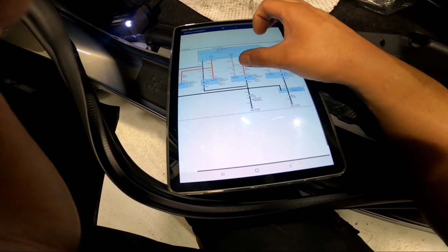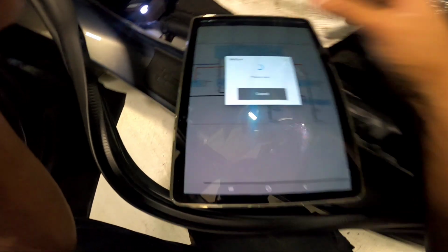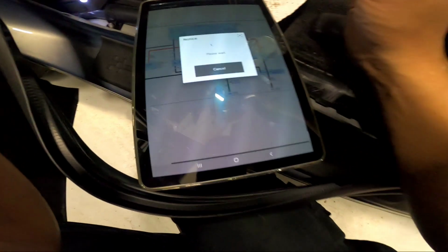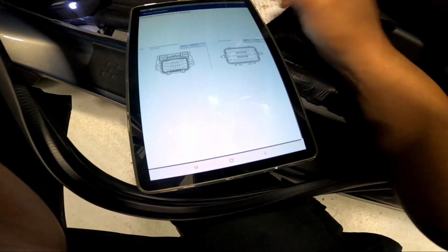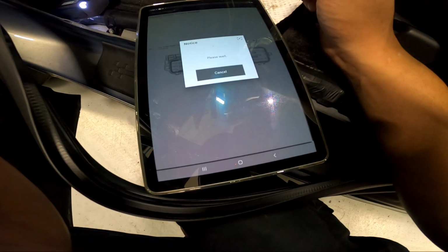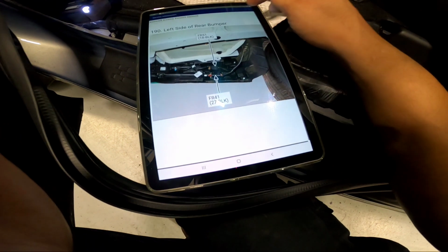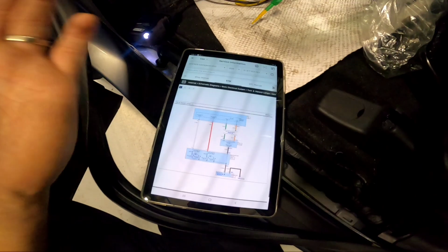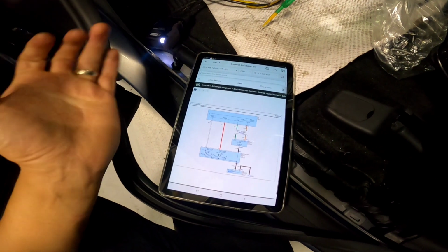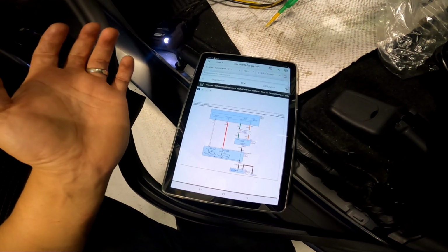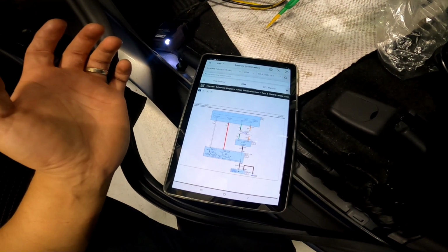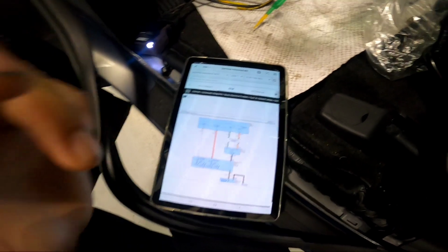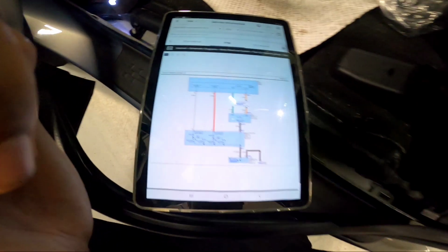So 41, that's different, I don't think that's the connector I took out. Yeah, FR51. So we're going to look for the FR51 and see what circuit is involved, because I already blew some water out. Let's see what else is going on in this circuit.